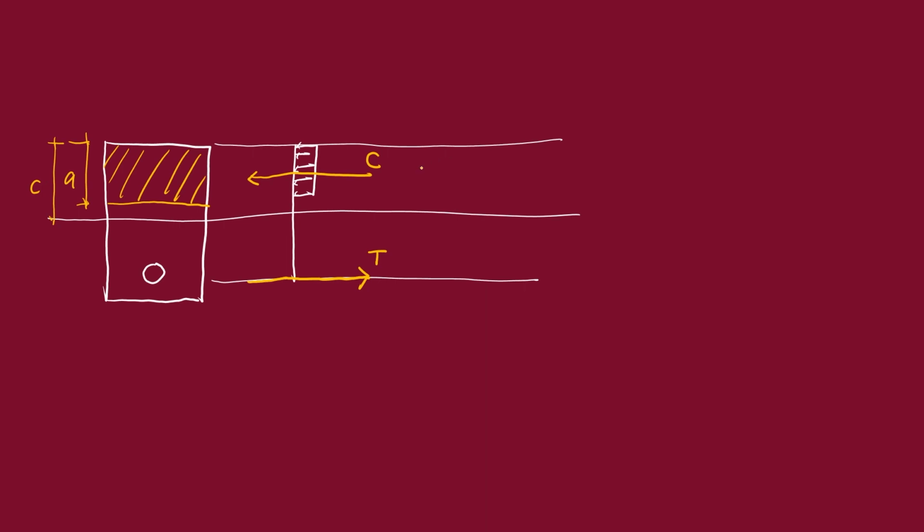So when do we have a doubly reinforced design? If we try to draw the strain diagram, it would look like this. The strain for concrete is 0.003. And the strain for tension, for steel, is equal to Fs over the modulus of elasticity of steel. That is the value for the strain in steel.